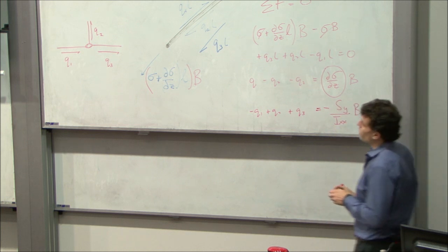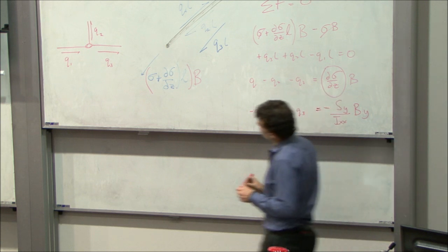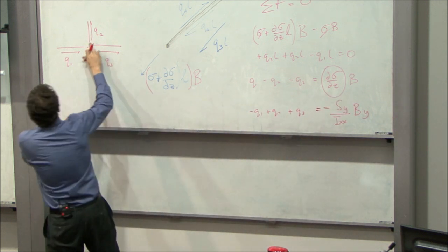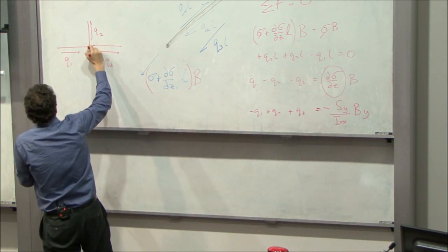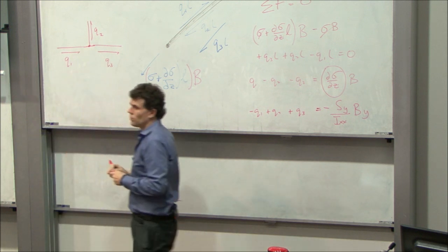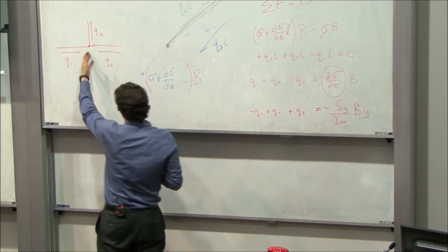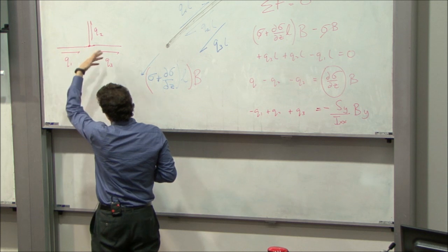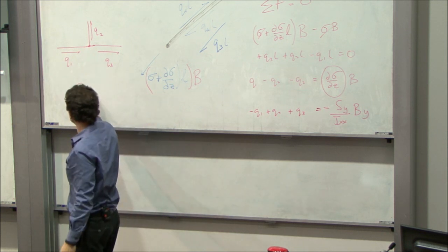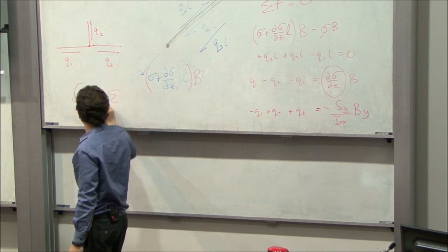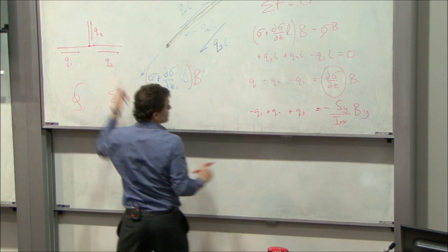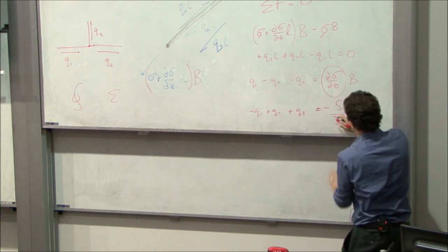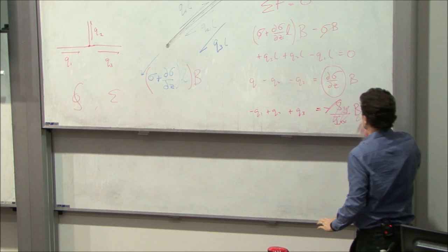So in a problem where we didn't have a boom area, where we've just got panels connecting to one another, like we would have done before we'd idealized the structure and we were calculating integrals instead of sums, this bit just goes to 0.